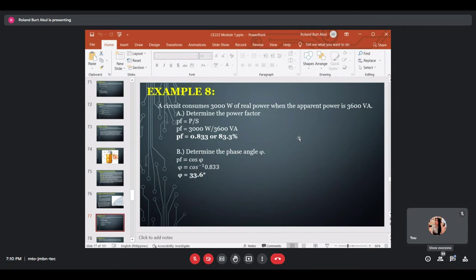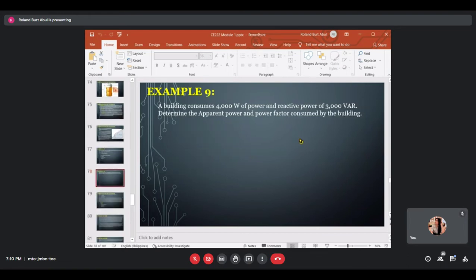So the power factor ratio is also equal to the cosine of the phase angle. For this reason, equipment nameplates and manufacturer information will frequently abbreviate the power factor as cosine phi. So considering that we have a right triangle, always remember the power factor here. Its adjacent side is the real power and the reactive power is on the opposite side. And its hypotenuse is the apparent power.